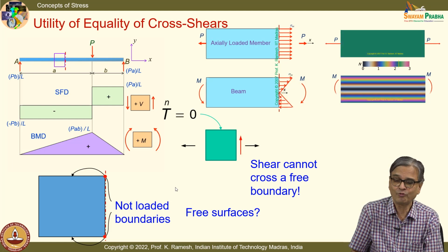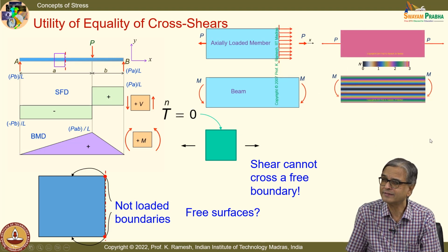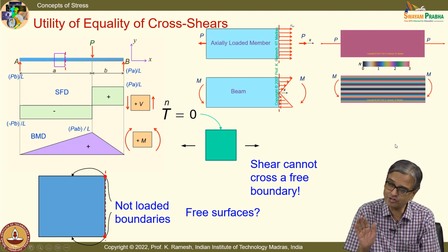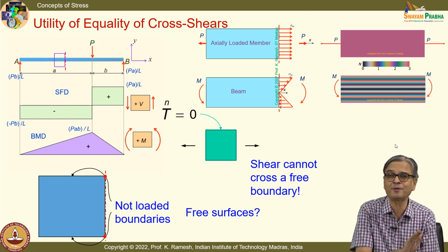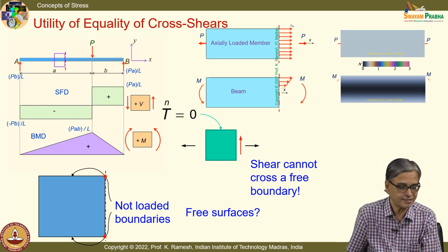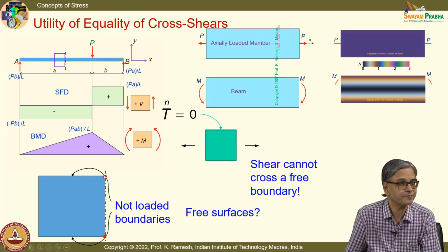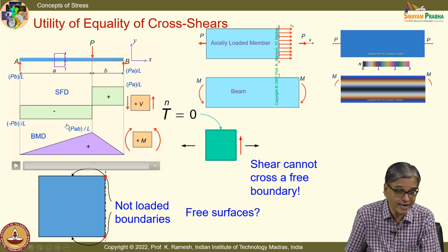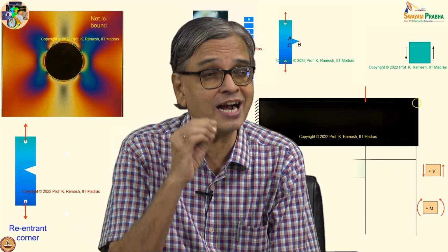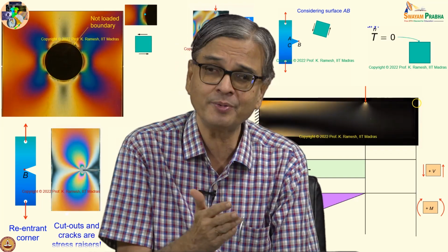I have already said whatever this is developed for a beam under uniform bending, there is no shear stress acting on it. I said this solution is applicable to this problem as well, which we call engineering analysis of beams. Now the question is, I am looking at a point which is sitting on the surface. It cannot have a shear stress even though I am applying a shear force. The distribution has to be such, it should start at 0, but the resultant will match with the shear force. Resultant has to match because the equilibrium should exist. That should not be violated.